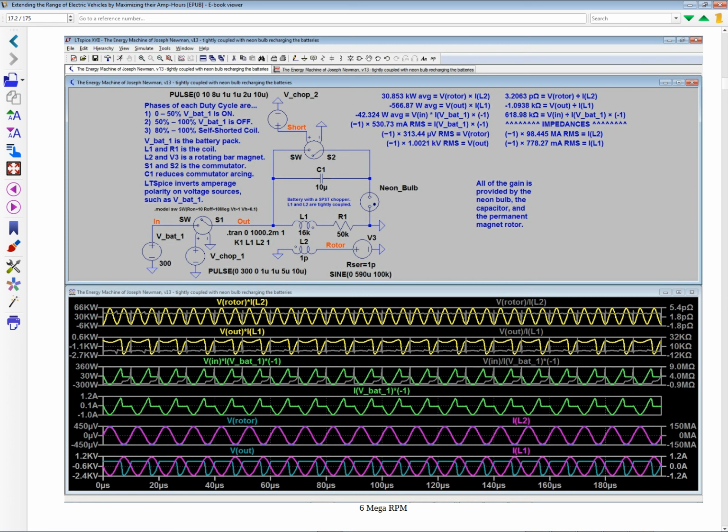And then when I turned my attention back to it, I decided, you know what, I know what this is suggesting. So why don't I just go ahead and start working on it again? It was suggesting, first of all, that I had a complicated design. I have all these grounds, and they're all common grounds, and it makes things complicated. So I simplified the circuit by uniting all the common grounds, and then I realized the circuit has a short.